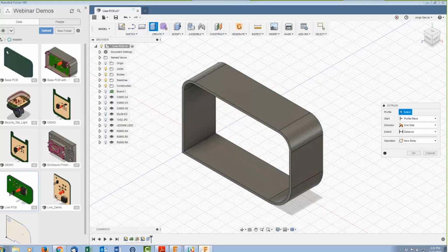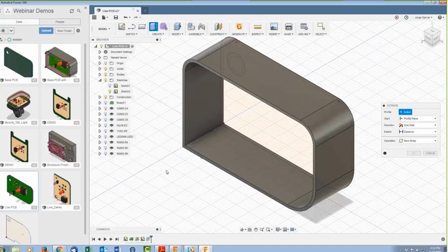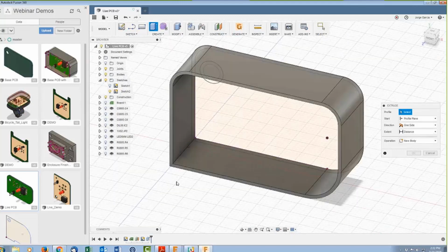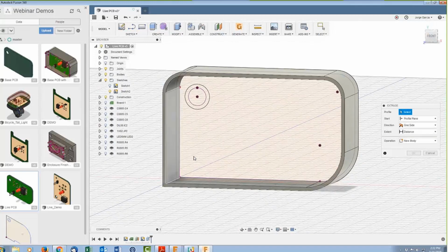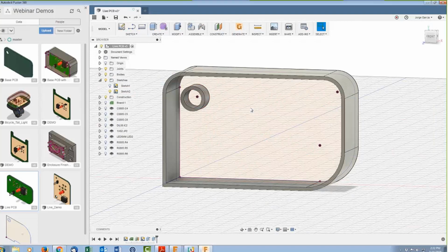Create the extrude. Let me make sure that the sketch is on so we can see it. To do an orbit operation, you just hold down Shift and middle click. And you have to hold down the middle click to get it to rotate. And it can be a little bit fishy sometimes. Okay, so this one, we're going to extrude that. Again, it's in the wrong direction. I'm going to take it 5 millimeters, -5. And we'll see that we have our little hole for where the bolt would go.